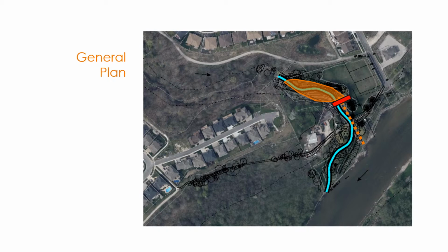All of that is going to be replaced by a natural system that is going to meander through a constructed valley and enter into the Grand River downstream of its previous confluence. We were able to reduce the slope somewhat in the system by extending the length of the channel, but as you can see, there's still a pretty intense valley curve happening here.